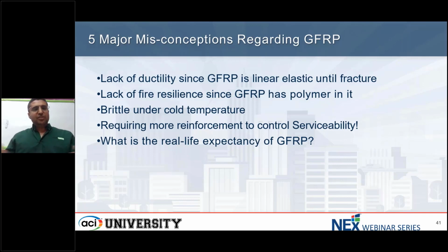These misconceptions have been gathered from experience. People say, "Well, great material, great choice, great durability, but fiberglass rebars are not ductile materials. They're linear elastic to failure, and this is a big problem." So I'm going to talk about that.